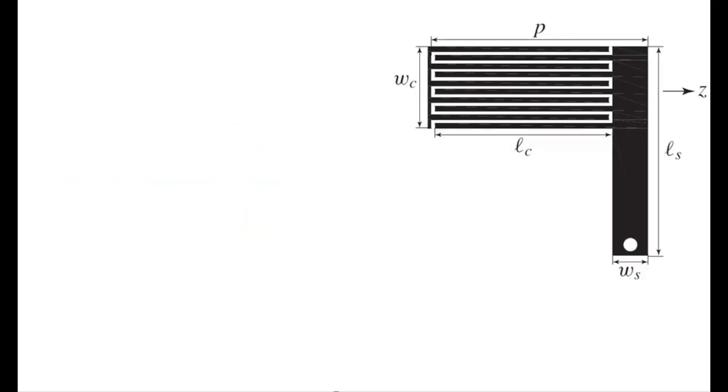Now first we describe the CRLH metamaterial. CRLH metamaterials are composite right left hand metamaterials, with right hand and left hand wave propagation characteristics within the same unit cell. In a single unit cell, we have right hand wave propagation and left hand wave propagation. CRLH metamaterials are always made by interdigital capacitor, stub inductor, and microstrip transmission lines.